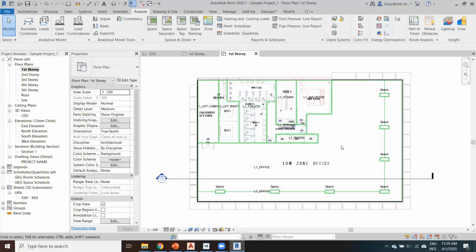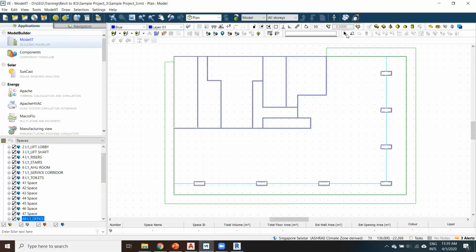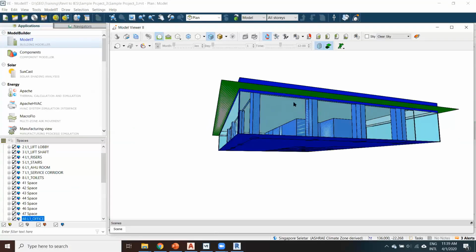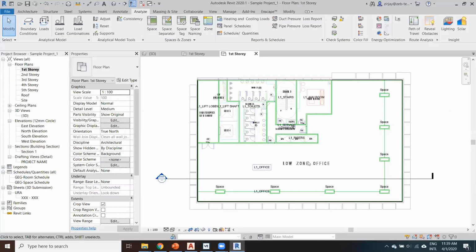And once you start doing it, you'll get the hang of it. It becomes like a game, where you're able to create something that looks clean once it's in IES. And you may have to go back and forth from Revit to IES, export gbxml, and check whether it's correct in IES.